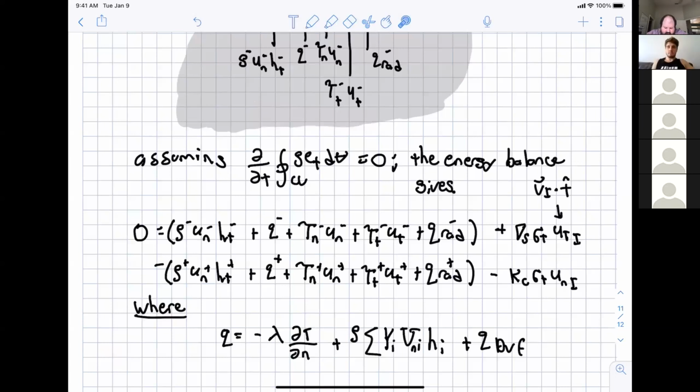And then when we start seeing the applications of these jump conditions, if it's for a vaporizing gas liquid droplet, you'll see these interfacial boundary conditions being used. Dr. Jackson uses them in his solid propellant combustion code all the time. And so all of these interfacial boundary conditions are baked into a whole lot of codes, and your second computer project will utilize some of those effects to model a burning propellant using a detailed chemical reaction mechanism. Okay, so are there any questions on the interfacial boundary conditions?